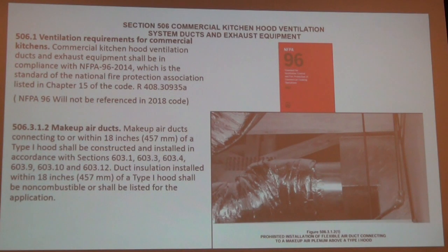The concern here is, I don't see them too often, but sometimes I do, where the makeup air actually comes into the cavity of the hood suppression system. There has to be a fire damper in that hood where the air comes into the plenum.